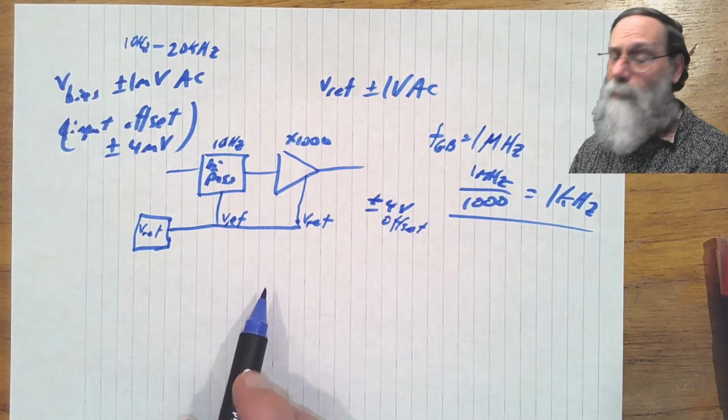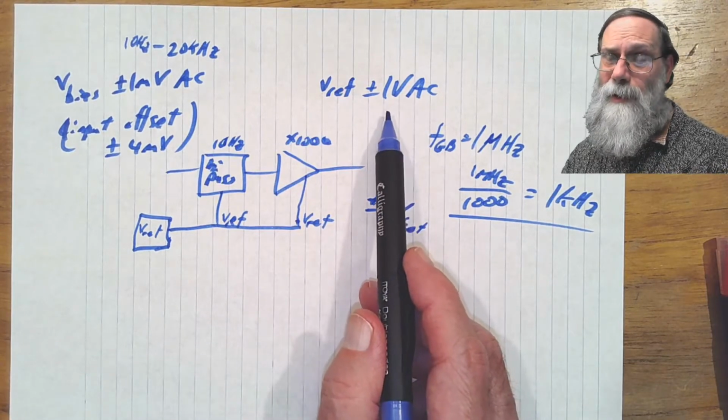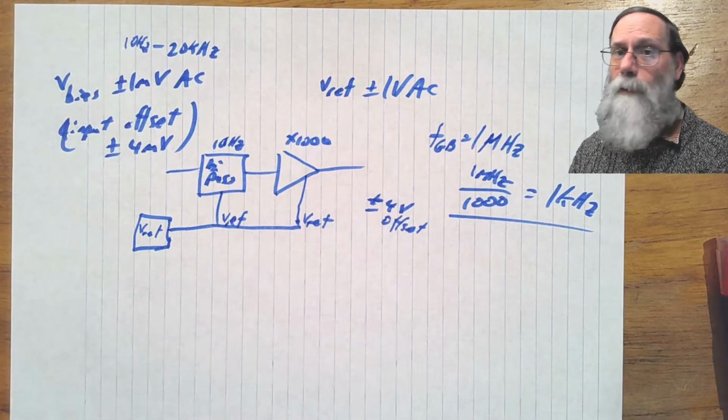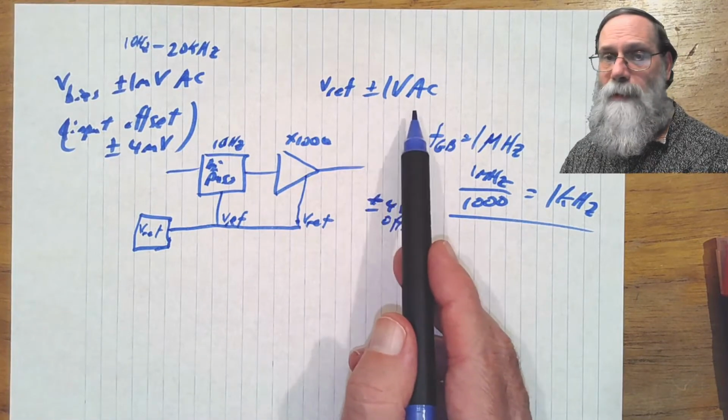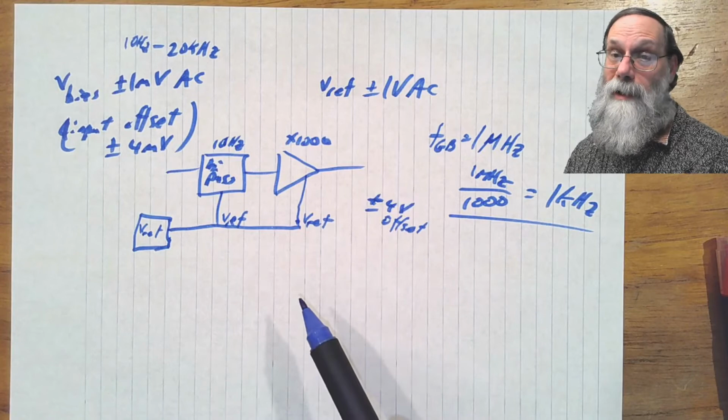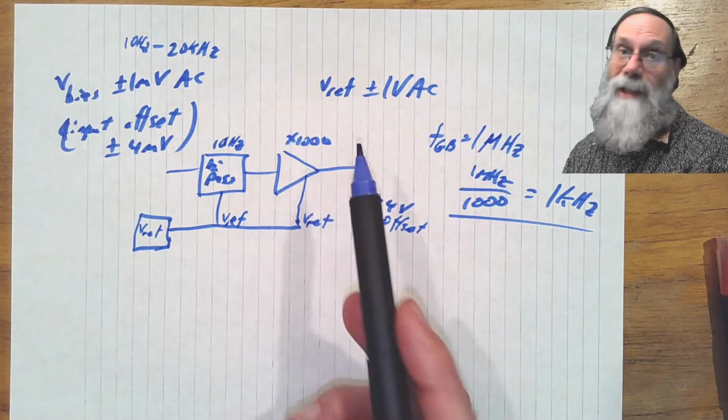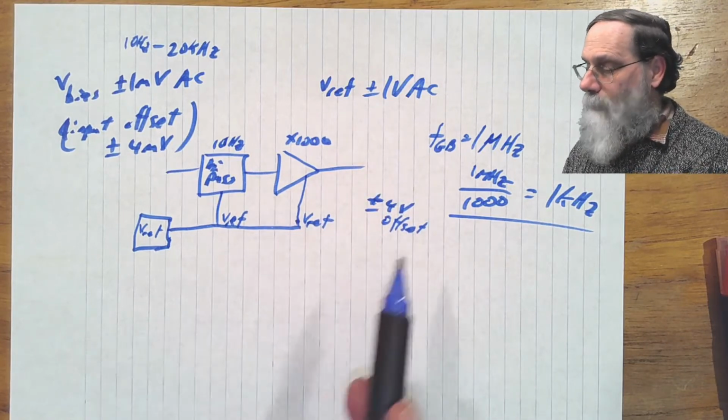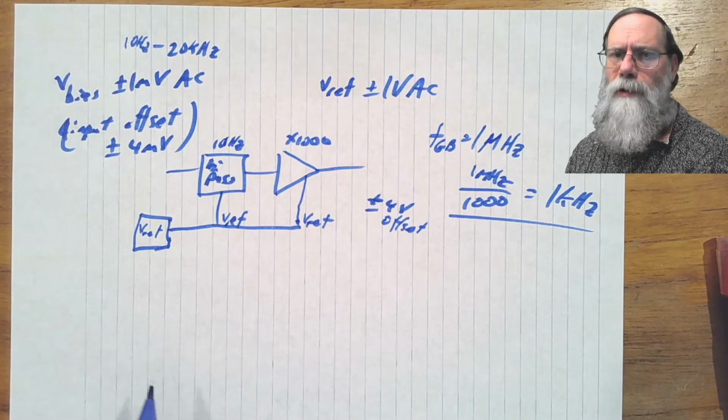And that's not very good if our analog to digital converter was only going to be taking stuff with a little over 2 volt range. So, if we had that much extra range in the analog to digital converter, we would have asked for a bigger gain. So, we're running into trouble here.